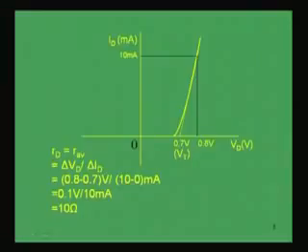So, this difference between the currents at the respective points is 10 milliampere minus 0 milliampere, which is nothing but 10 milliampere. So, we get this ratio between 0.1 volt and 10 milliampere, that will give us 10 ohm. So, the average resistance for this particular case we can find out as 10 ohm.